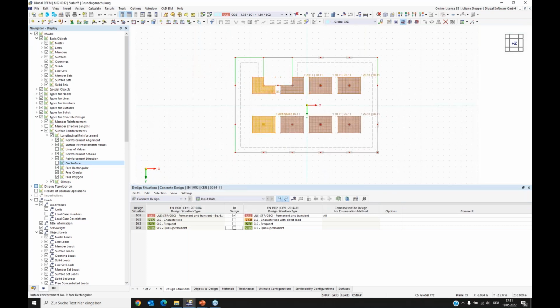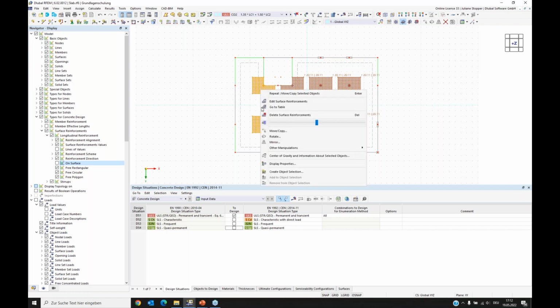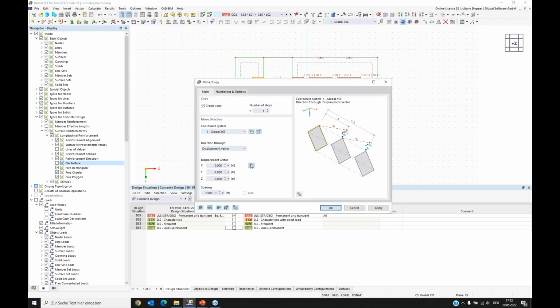And also I want to put here some additional reinforcement. It's due to the change of stiffness. We have here the supports, and here's no support. Here's the L-beam, and again here comes supports. We also have some singularities here. So I also put a copy there.